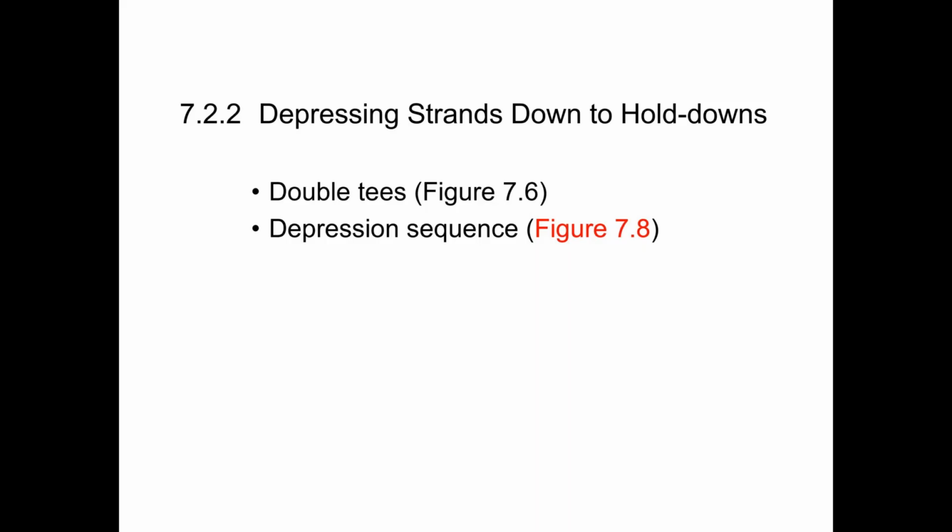They're generally greased so that they come out of the concrete easily, so that the depressor pin can be used multiple times. The only thing that is cast within the concrete and remains is the fork that's shown in figure 7.7b. So that remains in the concrete at the hold down location. Right, so that's the typical way of manufacturing draped strand double T's.